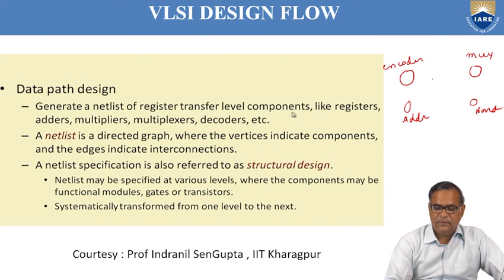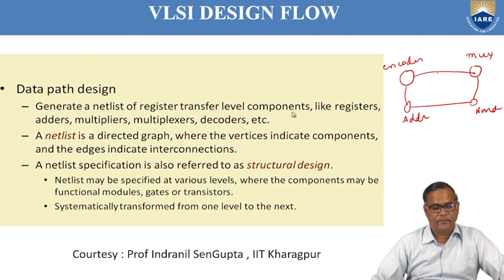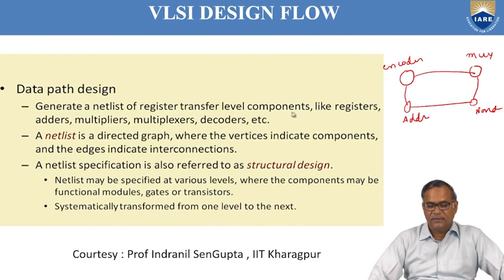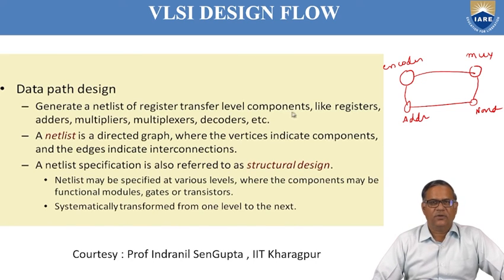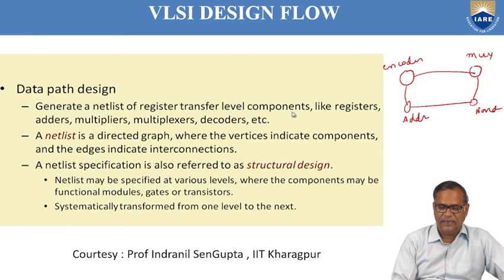So these are all the vertices, and these are the connections between these components. These are the nets. So the netlist is a directed graph where the vertices indicate the components and the edges indicate the interconnections. And a netlist specification is also called the structural design.